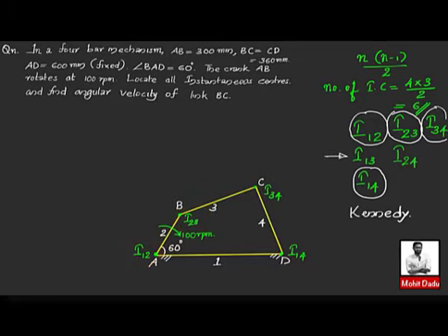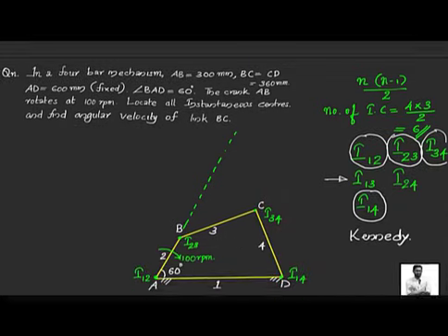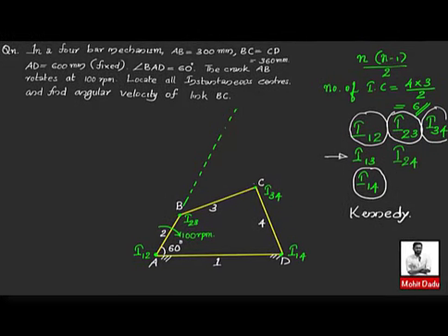So you can have a straight line which is extended in this direction. And similarly, if you are looking here, you are having I34 and I14. Out of that, if the number 4 is going, then you are having I13. So in this line also I13 will be coming. So you can have the line extended, so that will be giving the intersecting point at this point. So this will be the instantaneous center I13, that you can obtain using Kennedy's theorem. In a similar way, now you have located I13.